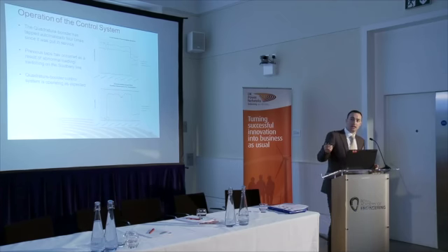And what you can see here, maybe not so clearly from the graph, is that a tap occurred on the 21st of September around midday. At this point, you can see from the top graph that there was a significant step change in the power flows through the two circuits. And you can see to a certain degree that they are much closer aligned.